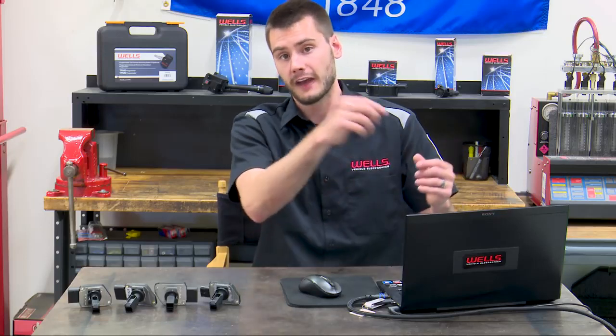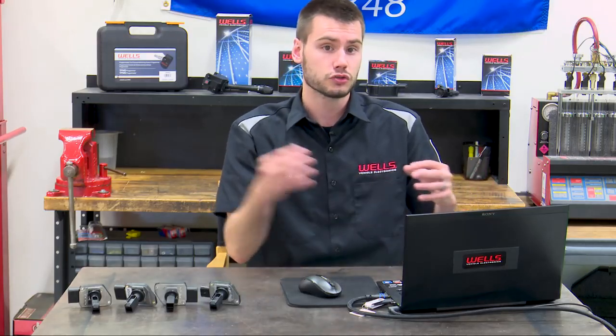A rich condition, because what is our purge solenoid doing? It's connected to our intake manifold, stuck open. It would draw vacuum on the evap system down the hose to the charcoal canister. If that charcoal canister is containing vapors at that point, those vapors would be drawn up into our intake manifold, and the PCM is not commanding our purge solenoid at this point. Say we're just at idle. Our purge solenoid is stuck open, drawing those fuel vapors in and causing a lack of oxygen past our oxygen sensors, right? We're polluting that with excessive fuel. The oxygen sensors are reading a lack of oxygen, giving us a rich condition.